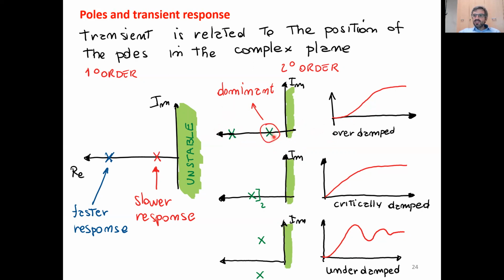Then if you change these omega n and z values, you could have these 2 poles coincident. So a solution in which the square root of that term is 0, and they are both real, and this is called critically damped. The previous one was the over damped response. This is a critically damped response. You don't have the belly anymore here. It's almost like a first order system.